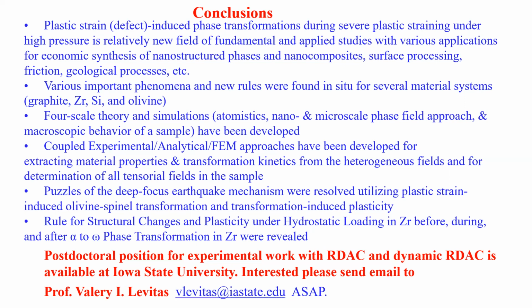Yeah, we don't do shock loading, but now we have started dynamic experiments with a rotational diamond anvil cell. We expect a rotation up to 4,000 rotations per minute, and the estimated strain rate is 10^4 per second maximum. The question is how plastic deformation produced through dynamic shock and through this rotational diamond anvil cell will be different. Can we quantify deformation?